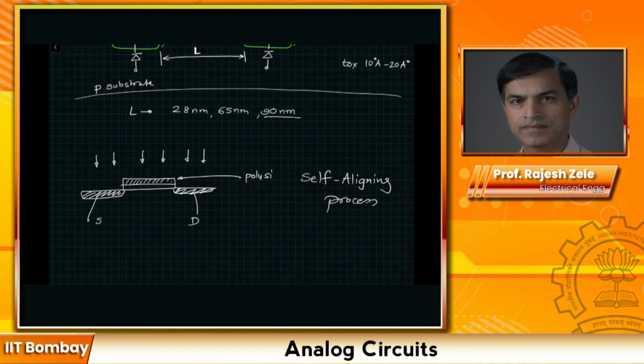However, metal was deposited separately and the metal would move around, so you have to leave a lot of clearance in the size of the device. Whereas when you use polysilicon, the polysilicon gets doped by the source and drain region impurities and it becomes like a metal, as well as acting as a mask for defining the source and drain region. So this was an advantage with the polysilicon gate.